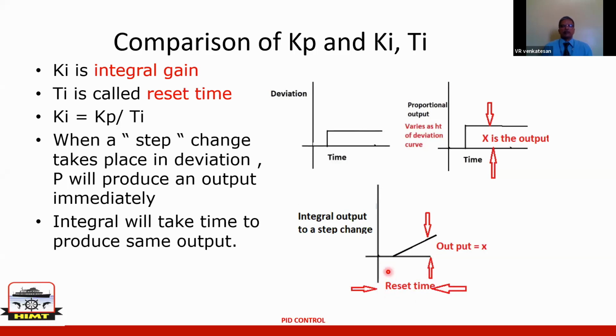Is this part clear? Because these are all practical steps which you can use on board a vessel to solve problems. Very often on board a vessel, control problems come under two main categories. Either the controller is too slow in response, or there's a lot of hunting. Have you seen this?